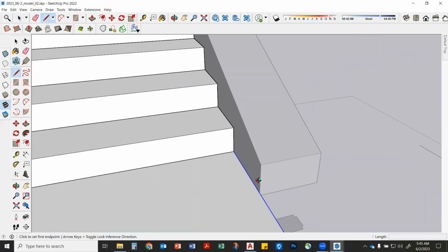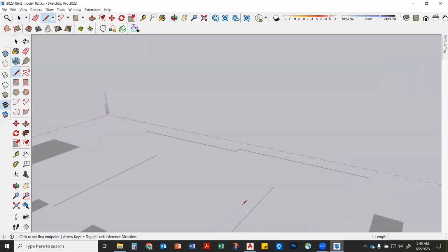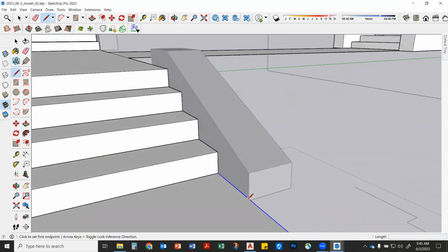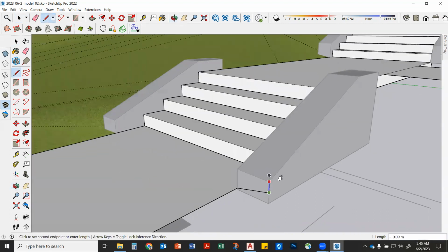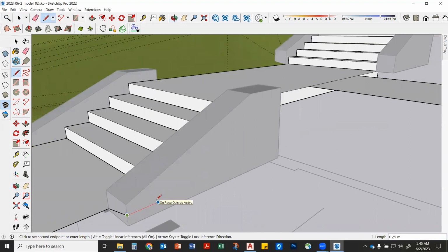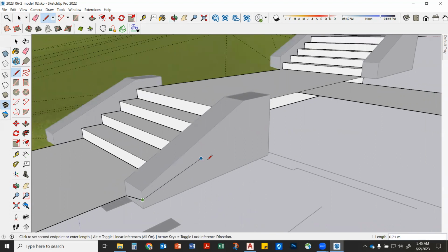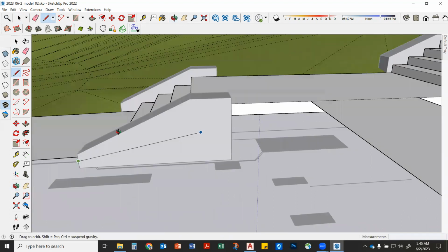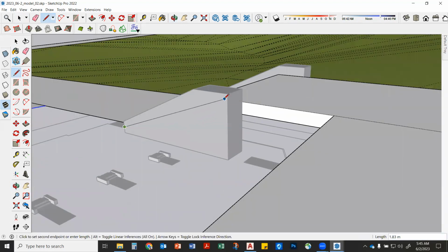So I'm going to draw out. I have to come in and clean this up a little bit. I'm going to draw a line. Whoa. Here, I'll have it slope up just a little bit, maybe. This is also when you're site grading, you actually start to sculpt things with your site grading. So watch, I know there's going to be a slope here because I have these stairs. The way I define this edge will be how I define the slope there, right?